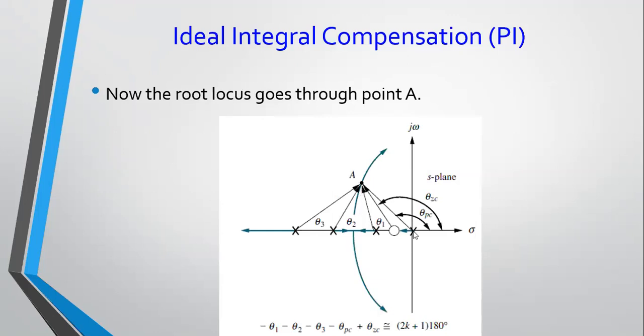So anyway, in terms of sketching a root locus, you see clearly that when you add this pole here and a zero close to it, the path from that new pole simply goes to the zero, and then you expect the root locus not to change. This is one way to look at it.